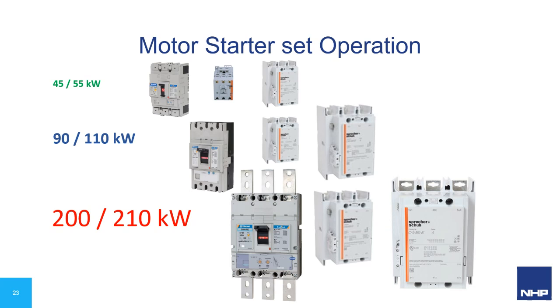The remedy seems easy. Just increase the size of the breaker and the problem is solved. Yeah, sure. But along with the requirements of Type 2 coordination in the mining industry, protection devices and the motor control equipment, any change in the breaker type or characteristic required a corresponding resizing of the motor contactor. This was due to the probable increase in the let-through energy and peak let-through during short circuit events, potentially destroying the contactor and overload set.